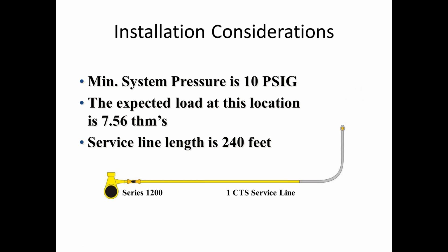Others don't. All these valves are tested for snap acting loads at 75% of that trip point, and some at even higher levels. So how quickly you open the valve is typically not as important as how far you open the valve.